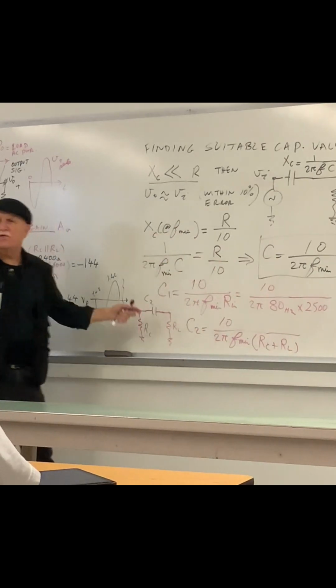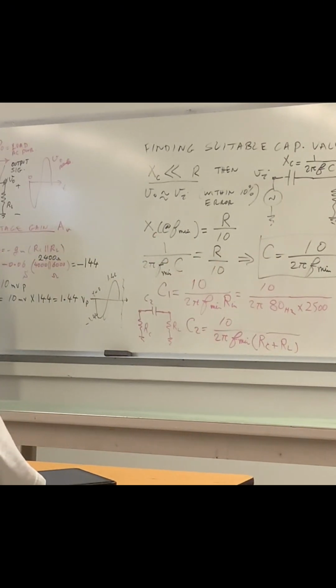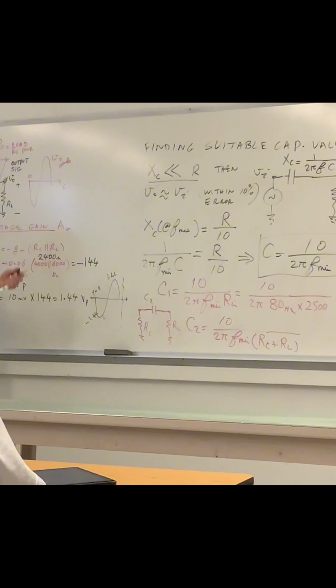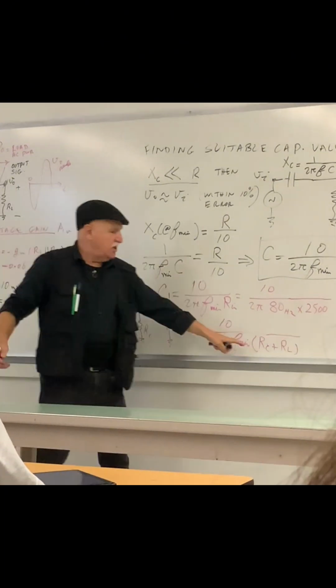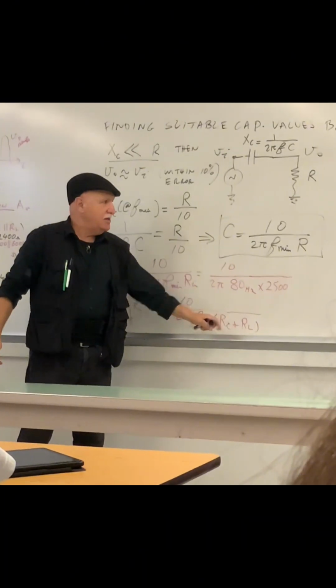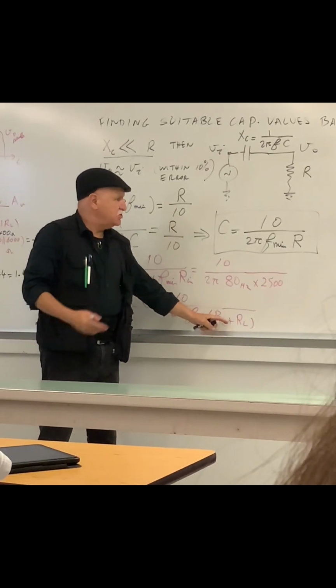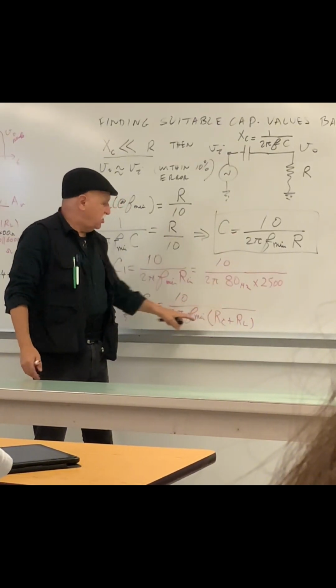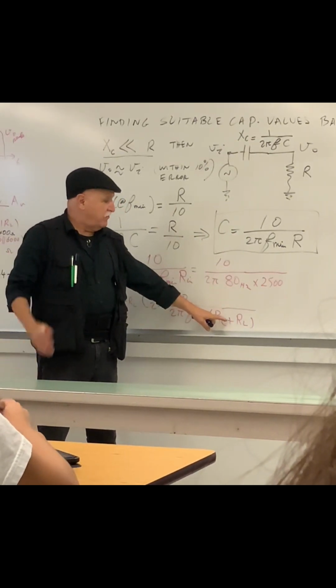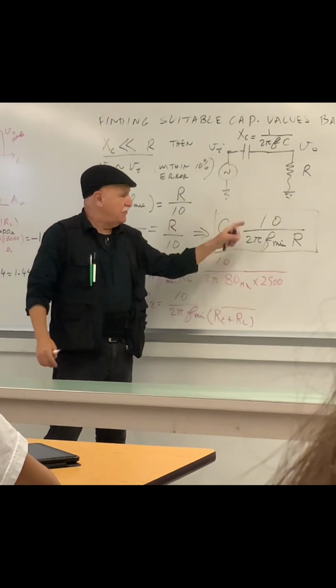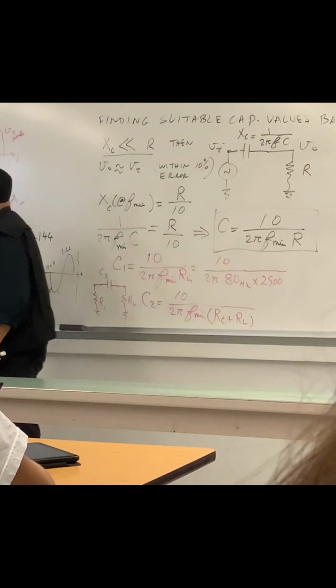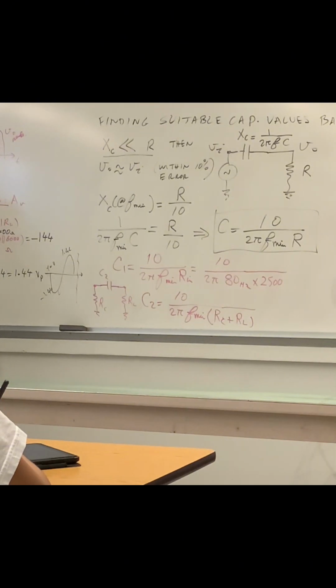Finished. You have formulas, so you can determine the capacitor. Stick in the values. 4K here, 6K here, that's already 10K. So I'm guessing that this capacitor C2 will be 4 times smaller than this capacitor C1 because it's a higher resistance over there. Stick it there, calculate.